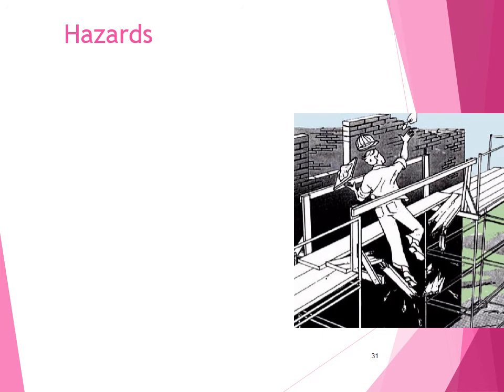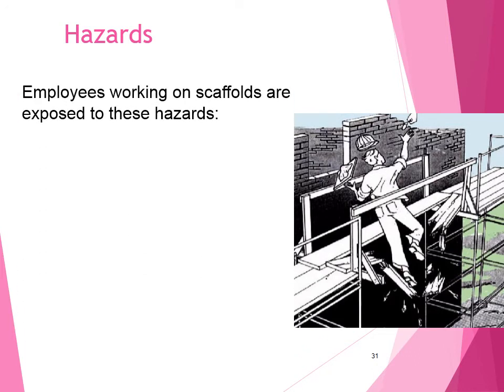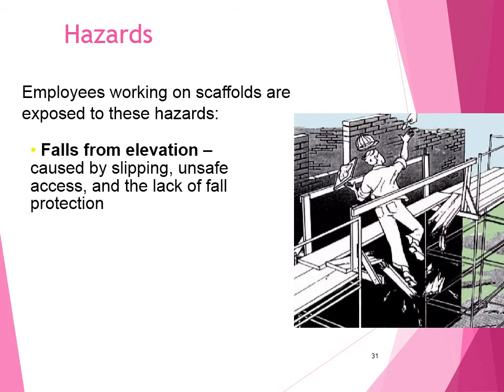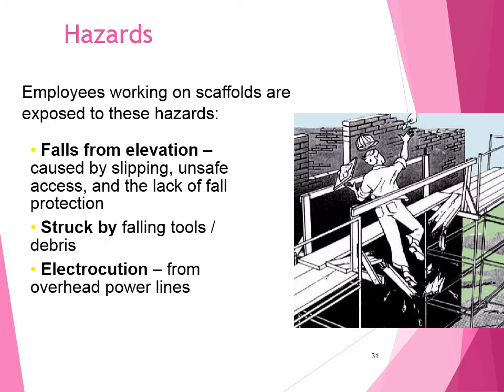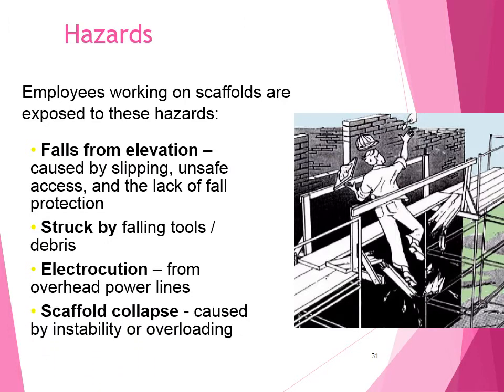Hazards. Employees working on scaffolds are exposed to these hazards. Falls from elevation, caused by slipping, unsafe access. Struck by falling tools from the top, electrocution from the overhead power lines. Scaffold collapse caused by instability, overloading, bad planking.